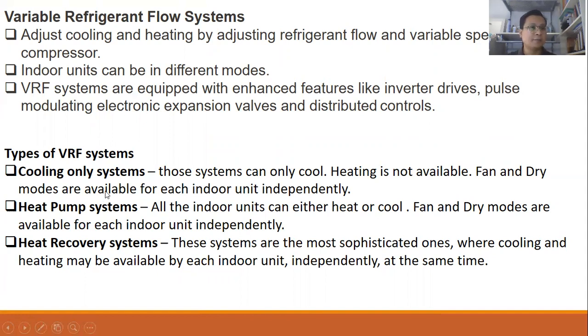Fan and dry modes are available for each indoor unit independently, so we can operate the system in separate rooms independently and control the condition of each unit differently, but only for cooling. So we cannot use this in winter conditions. This is only for summer.